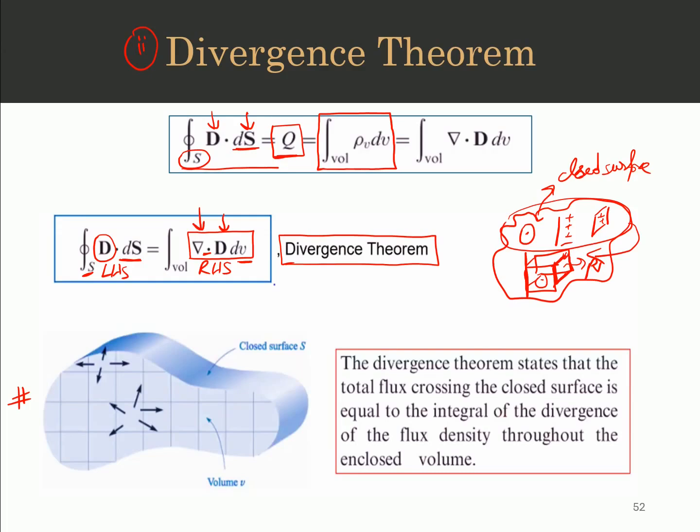Thus we can say whatever the charge enclosed by this volume, whether it's a point charge, a line charge, or a surface charge, is going to be equal to the total electric flux that is leaving this surface. We know the electric flux leaving will be perpendicular to this surface everywhere. So this means that we can represent the electric flux that contains this charge also by the volume charge integral. We have already talked about this as well, and we have seen this mathematical representation visually over here. Now how does this volume charge relate to the final expression, or the fourth term in this equation?